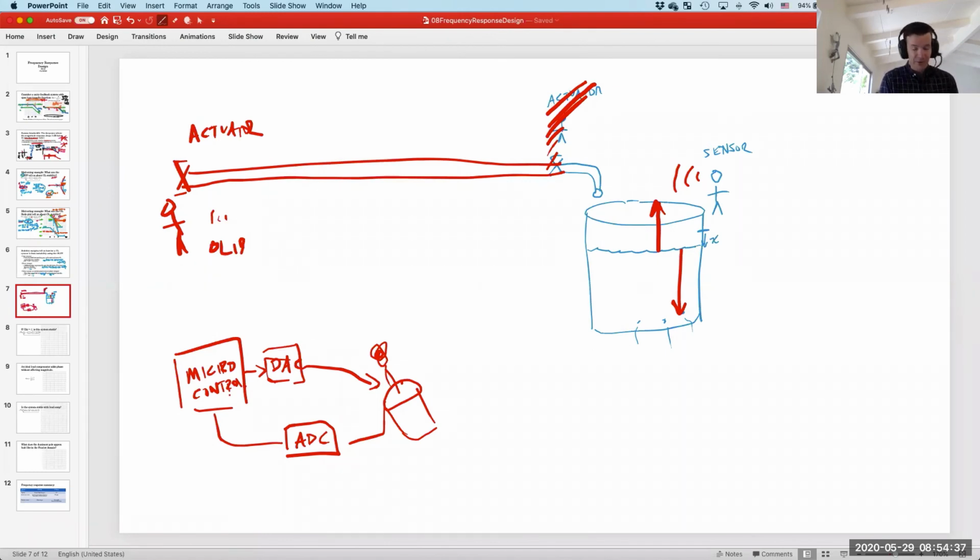And then I also don't know how long it takes the DAC to take the digital and convert it back to analog. All of these have time delays associated with them. We treat them as instantaneous, honestly. But if you stack enough of these up together, it's not going to be instantaneous anymore.